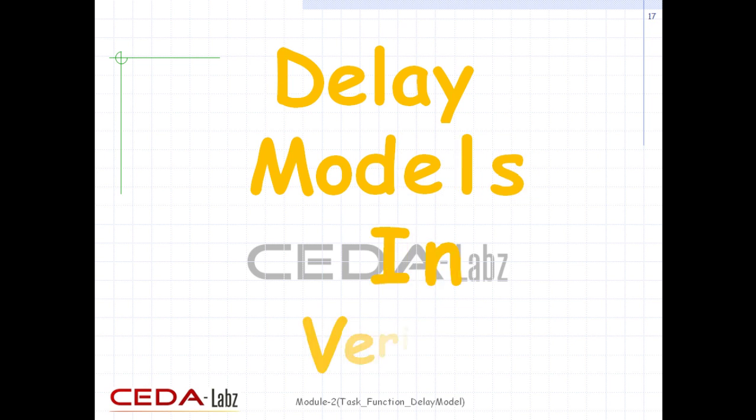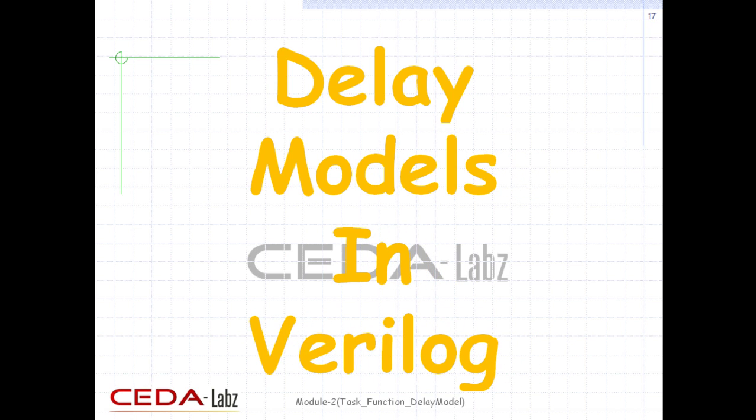Functional verification of hardware is used to verify functionality of the designed circuit. However, blocks in real hardware have delays associated with the logic elements and paths in them. Therefore, we must also check whether the circuit meets the timing requirements, given the delay specifications for the blocks. Checking timing requirements has become increasingly important as circuits have become smaller and faster. In this section, we will discuss how delays are controlled and specified in Verilog modules.